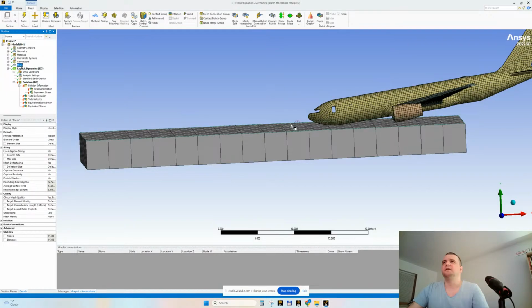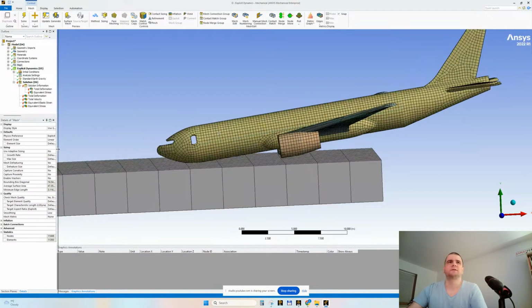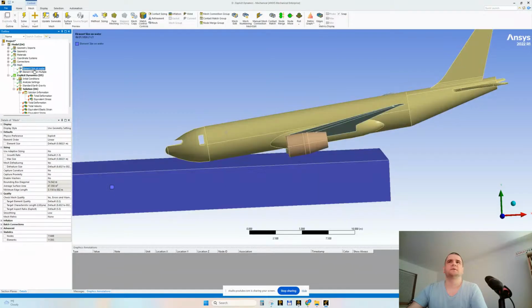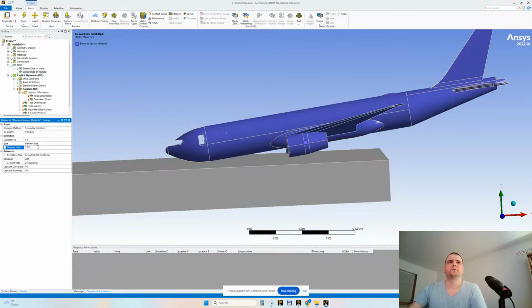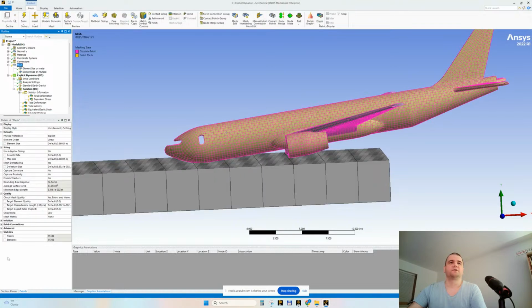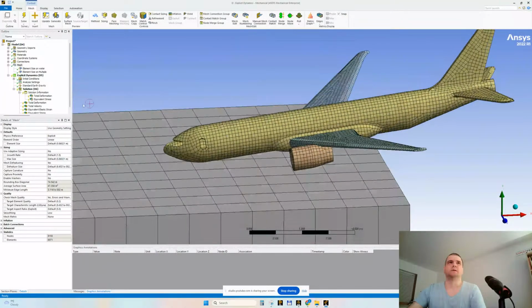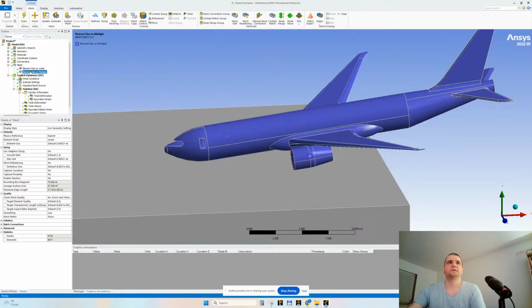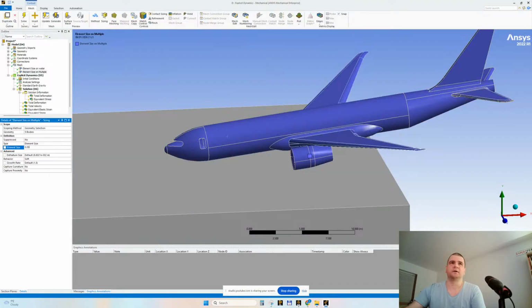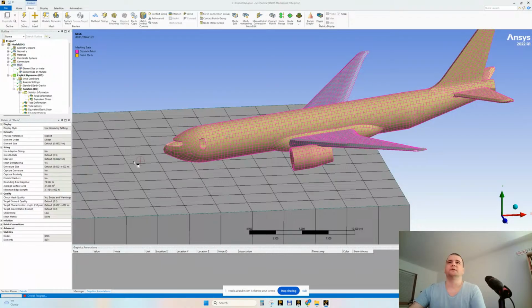Can I make this mesh a little more coarse? The mesh on the airplane, let's see, 0.25, can I make it 0.3? Now we have how much? We have 11,000 nodes. 8,000 nodes, yes. We're happy. Can I exaggerate a little? Let's see, what are we not doing for quicker solving?